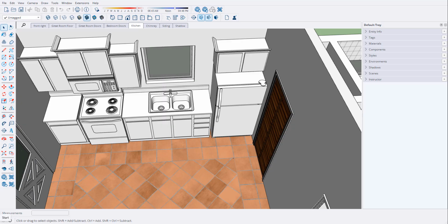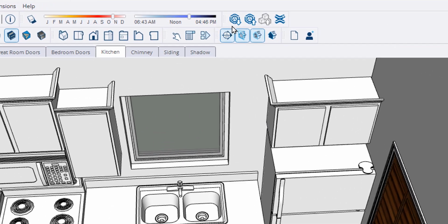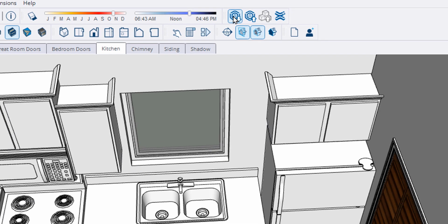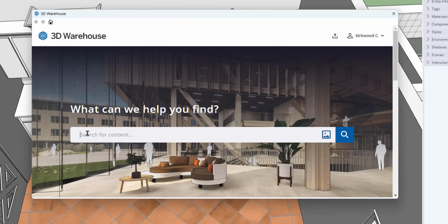Whenever deciding on materials to add for a project, you should always consider materials that actually exist in real life. One source to find them is the manufacturer's website. Another one is also the 3D warehouse. Let's say we're going to have a Formica countertop. I'm going to call it Formica Solid Surfacing. Let's say we want solid surfacing countertops for Formica. We're looking for that. Now, you could type different manufacturers, suppliers, and so forth, but we're going to use this one for this lecture.